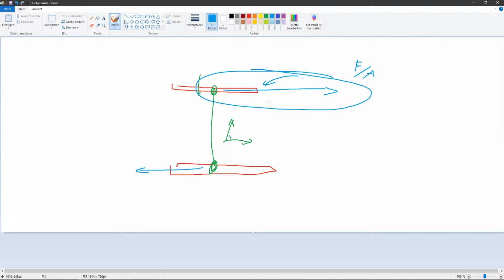So the 1D elements could be a thing to couple two RBEs together. At least, what I could do is make something like: if a rigid is connected to a bar or beam element, I could highlight that in the output and maybe sort the output by connected elements, so that the RBE elements which are connected to the same bar element are in the same place in the output file, and not just one at the top and one at the bottom.